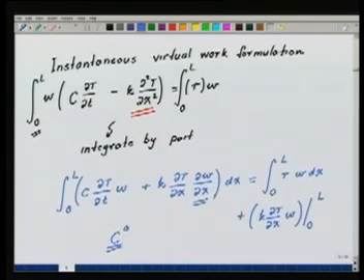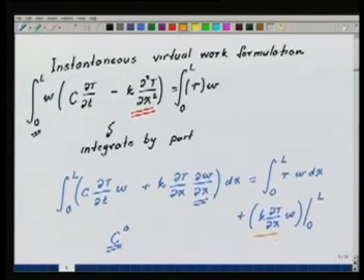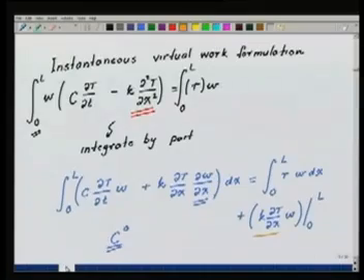And you see the boundary condition here, this is a term which is given at the two extremities of the member for all times. Remember that this boundary condition has to be expressed for all times. So the way we have drawn our figure, at x equal to 0 the temperature is maintained at the value T0 for all time, which means that at that end W has to be chosen to be equal to 0, because the temperature at any instant is known at that end.